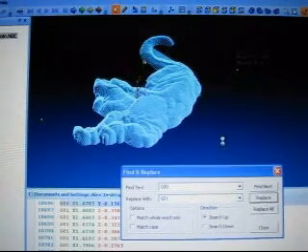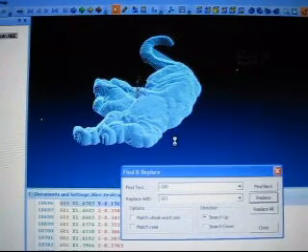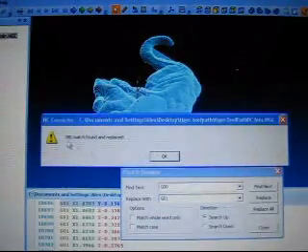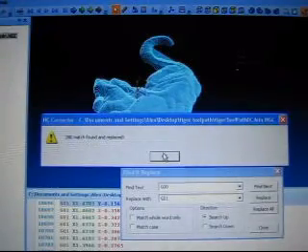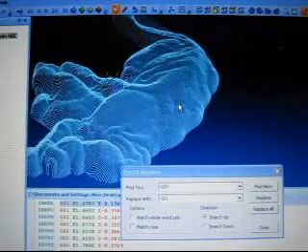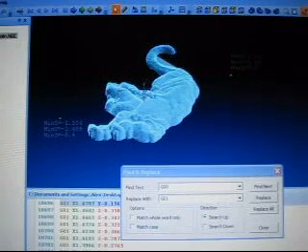You see that in action right there? It's replacing all of those rapid motions to feed rate, just like that. It's automatic. 280 matches found and replaced. Done. Isn't that beautiful? And I just go File, Save, and we're done.